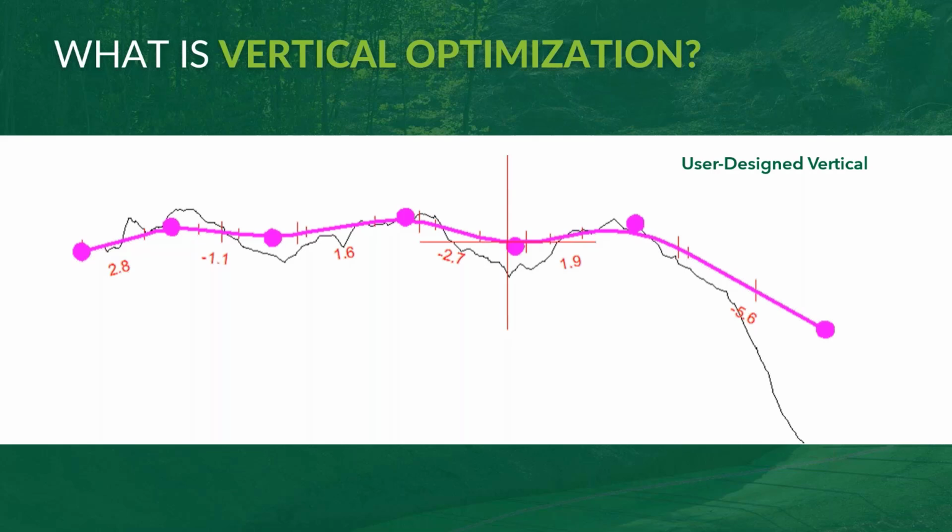Now, if you're able to use really fancy mathematics and computers, you can actually ask the tool to reduce the amount of earthworks that are being cut and filled, and behind the scenes, it's also solving the problem of where does the material go? Where does it come from? Where does it go to as you look to build your road?